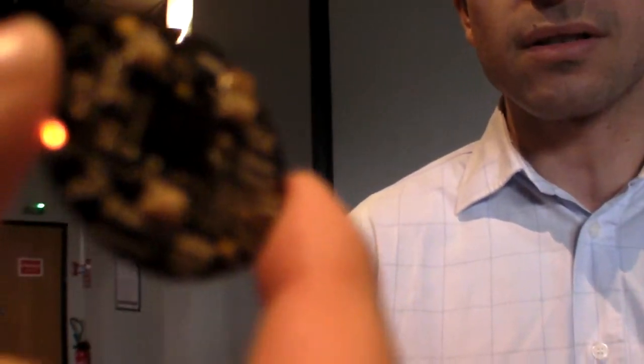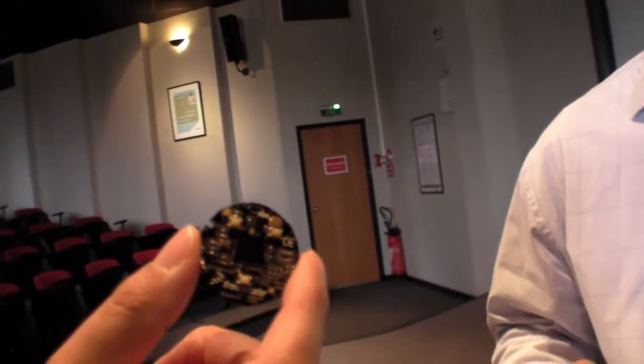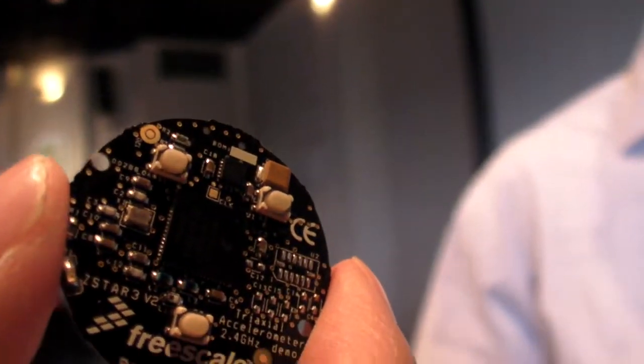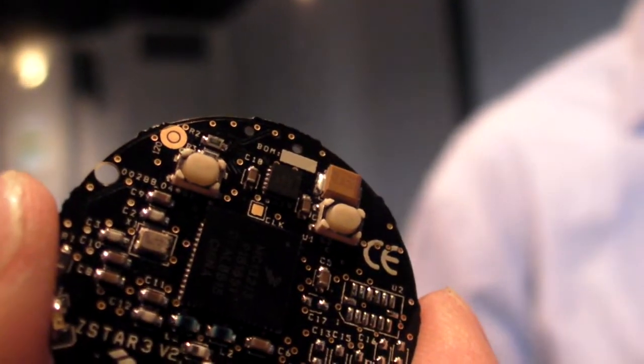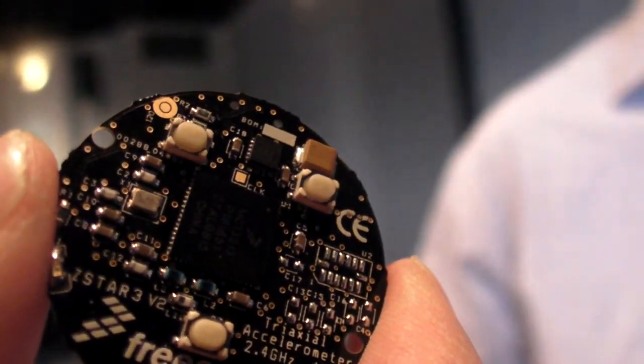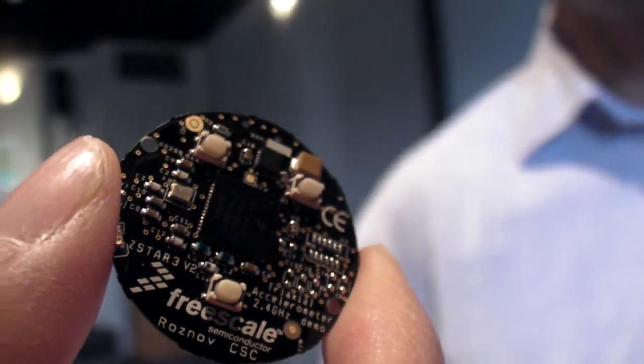In that chip, you have the G cell, which is sensing the motion, but as well you have an ASIC, a complete, I would say, digital processing unit inside the accelerometer, with a lot of smart functions that are embedded in the accelerometer. For sure that product can detect the acceleration data, but as well there is some embedded smart function in that product that can detect, for example, the static orientation, such as portrait landscape detection.